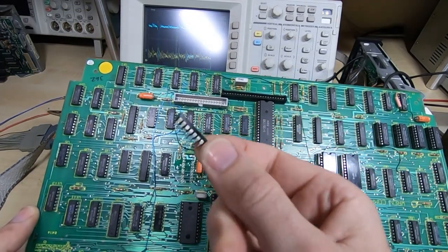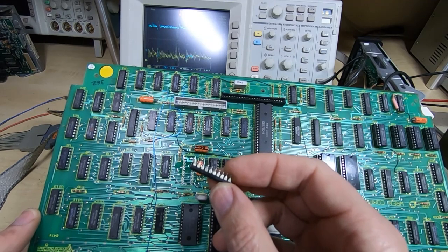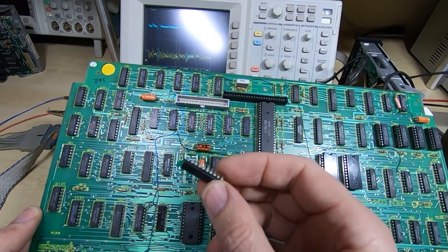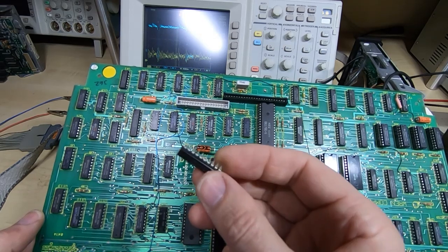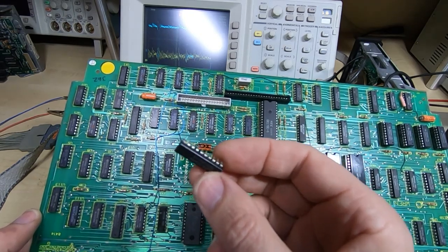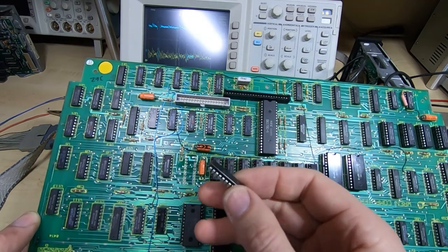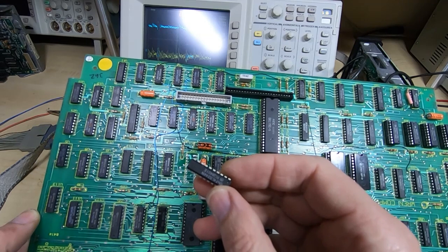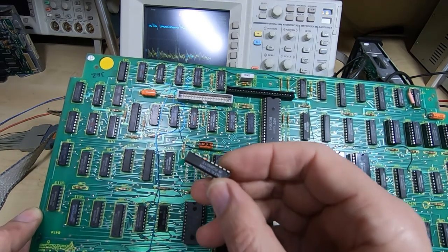Okay, so I've removed the chip. I tend to remove chips intact. I very rarely cut the pins off. I know some people prefer to cut the pins off and remove the pins one at a time, but I tend to remove devices and try not to damage them or overheat them. I want to know if they were actually faulty, and that just gives me more information for the future, and I can keep learning as I repair more and more devices.